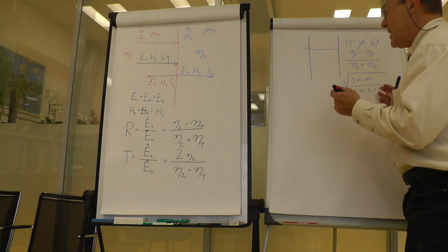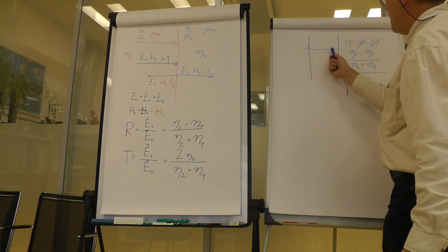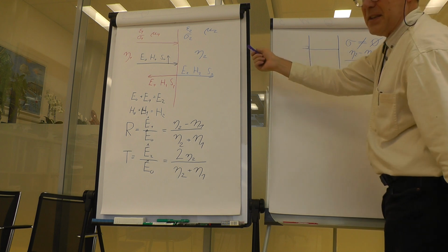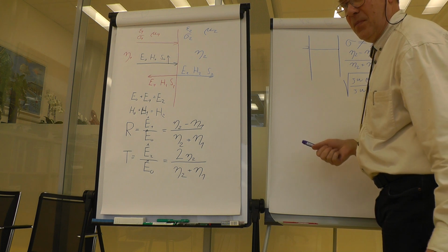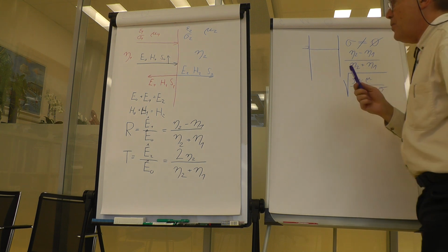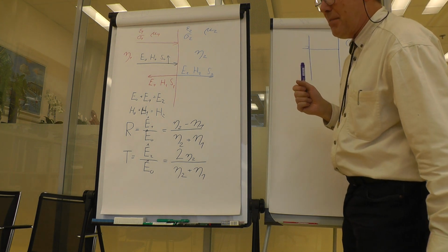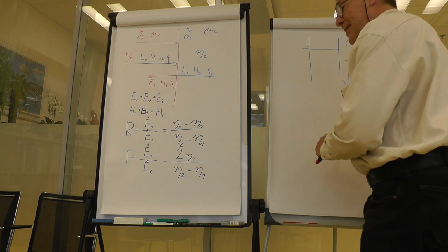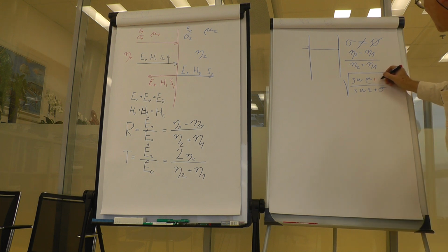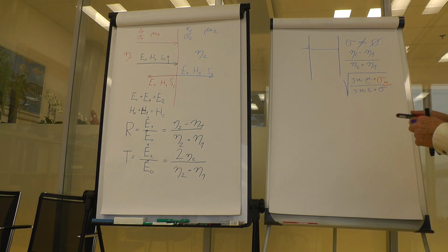If you increase losses, well, then the signal would be damped by reaching this metallic surface, but it would already reflect from this surface. So what's the achievement? Unless you find a material that has both magnetic and dielectric losses. But then you have to have also something which is denoted by the same letter as specific conductivity, but the dimension of this is inverse.